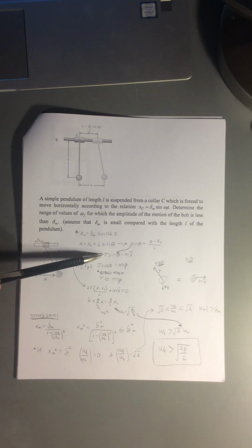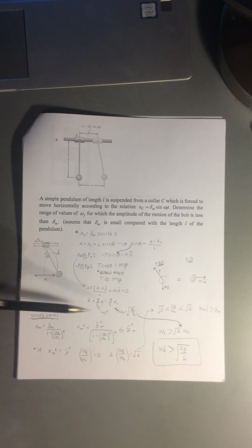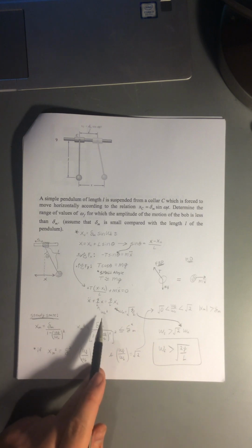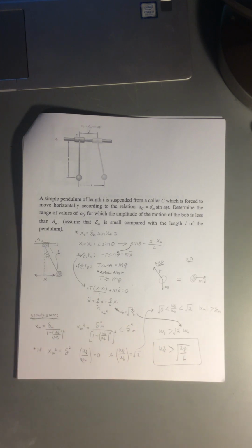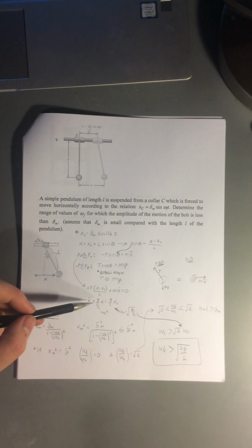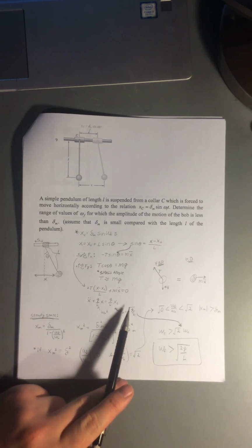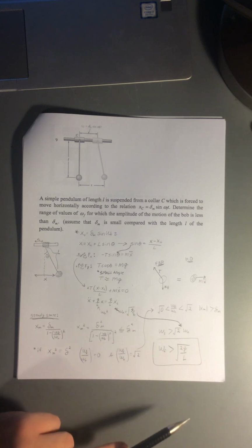Taking this term and plugging it in for sine of theta gives us this equation right here. I also added this term over to the other side to make it positive, which set it equal to 0. At this point we pretty much have our equation in the form that we like to see when we're solving these types of equations. And that's what gives us this equation here. Looking at this, we know that this term right here is the omega n term squared. Taking the square root of g over L tells us that omega n has to equal the square root of g over L.